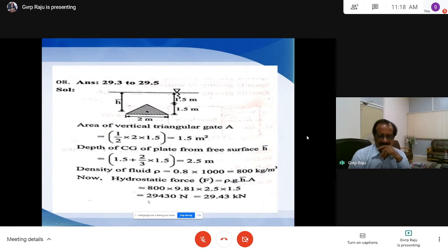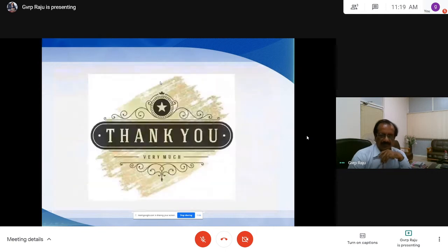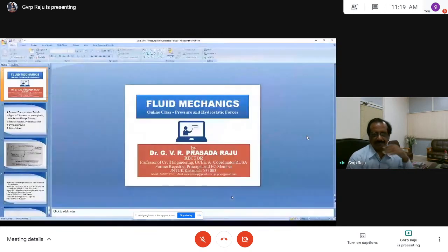The multiplication gives 29,430 newtons, and divided by 1000 it is 29.43 kilonewtons. For 29.43, you can give an answer between 29.3 and 29.5. So with this, we have discussed the chapter on hydrostatic force and pressure.